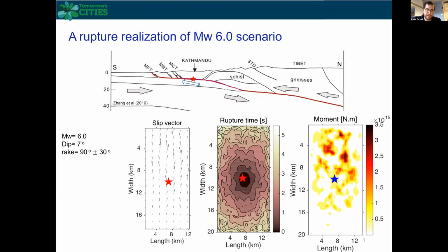of magnitude 6 under the Kathmandu Basin, and this is where the initiation point of the rupture is placed. It's based on judgment that these surfaces here have the potential to rupture. This work has been started in the sense that we will conduct simulations on the order of hundreds in order to encompass different types of ruptures that could occur, and also different locations of the rupture.